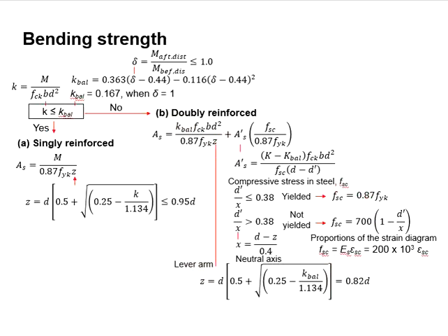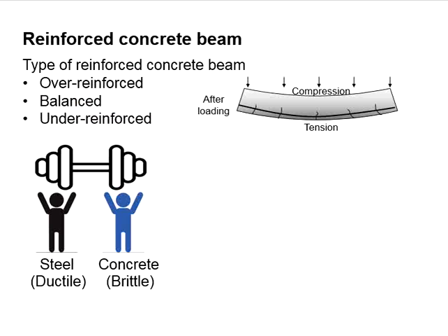As you can see, we want to ensure that reinforced concrete beams are always under reinforced, so that the member fails ductilely, giving us warning in the case of overloading, so that responsive actions can be made quickly before the actual failure of the member.